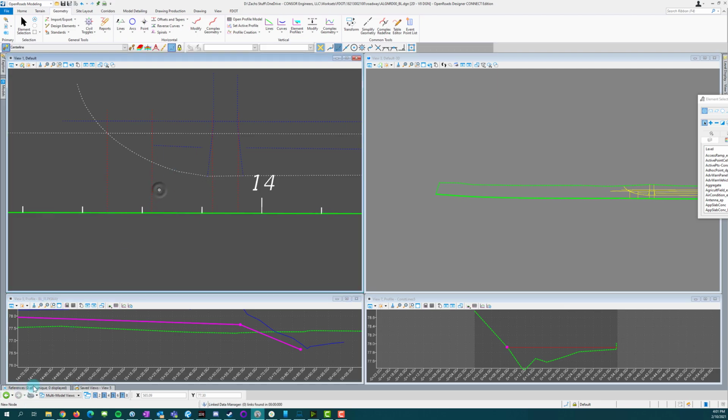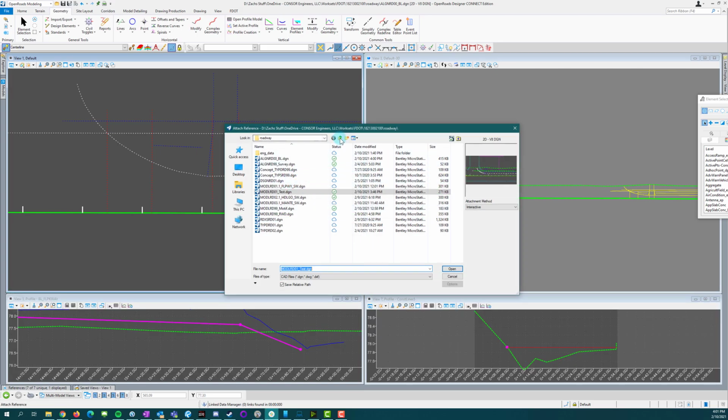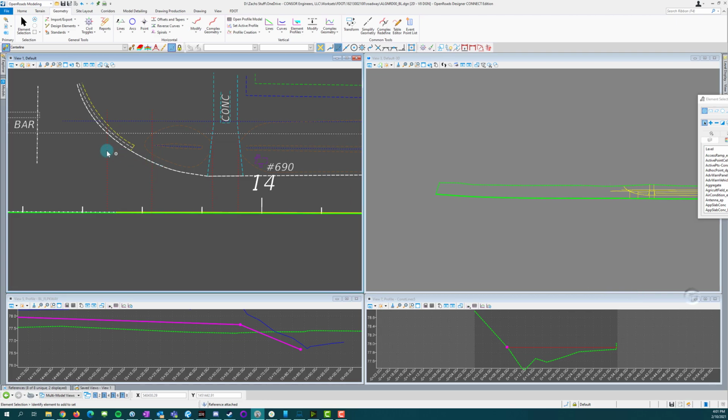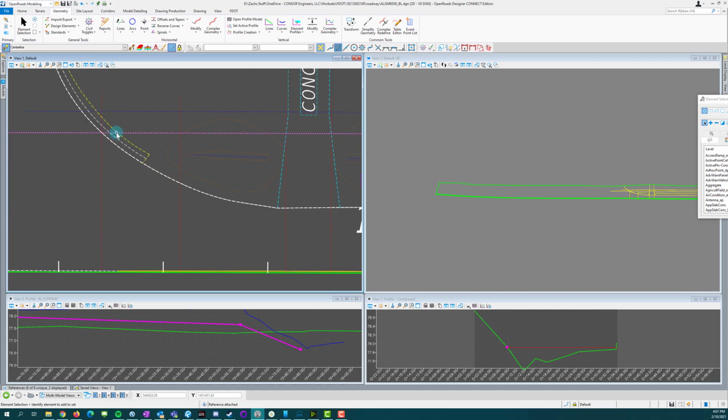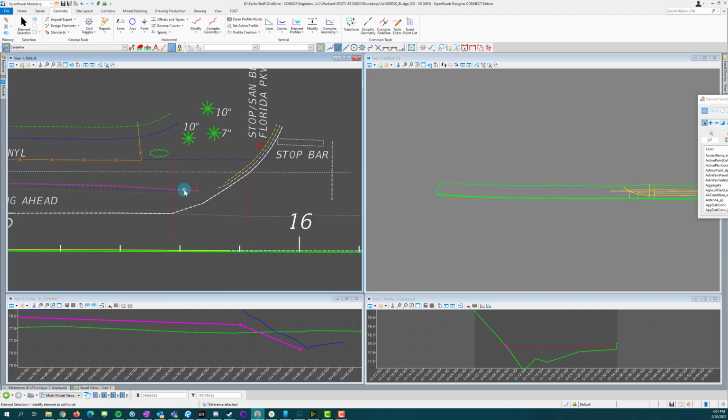And I believe this is curbed. Because this is curbed, I don't have topo attached. Survey topo. Because this is curbed back here, we're probably going to have to make some sort of curb ramp, and the sidewalk will be here, and then we'll have to wrap this around and extend this curb out a little bit further. So both of these have curb, so we'll have to take that into account too. There's definitely going to be a ramp here as we come into here.